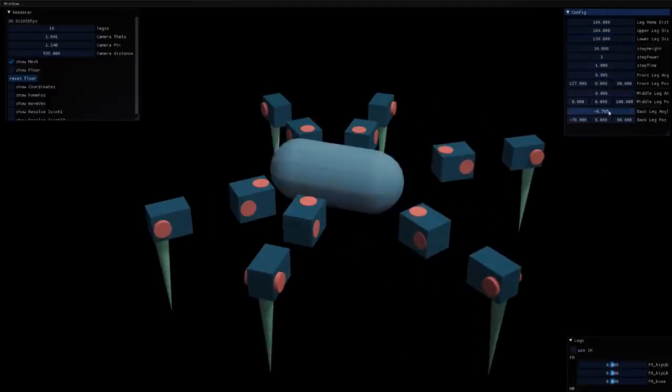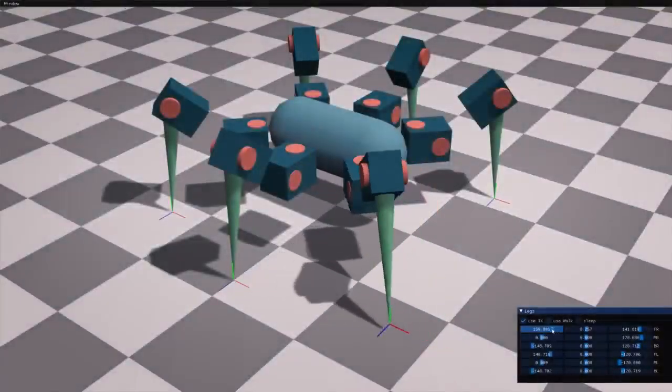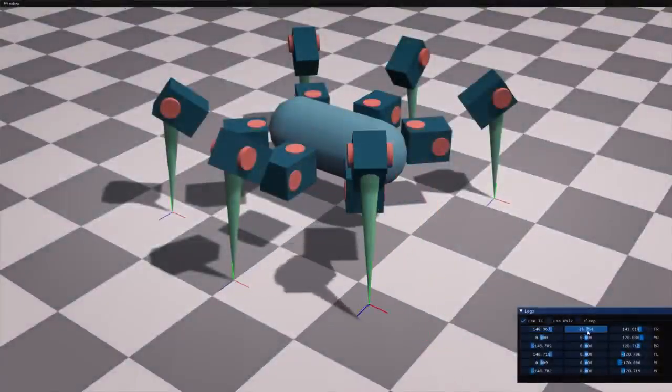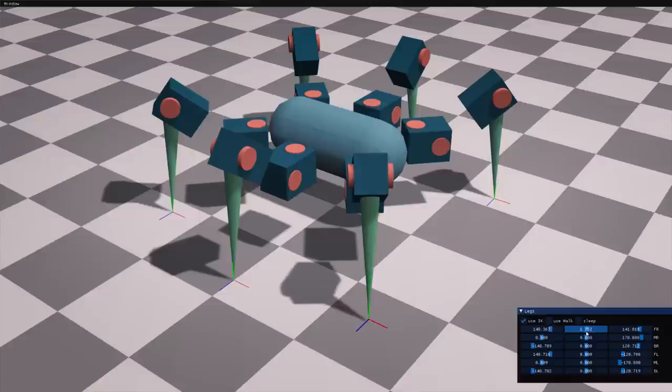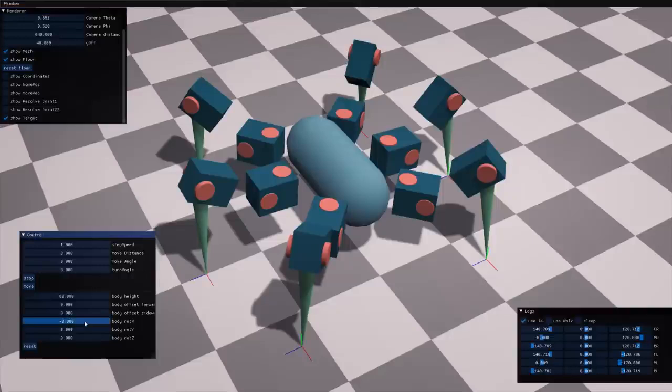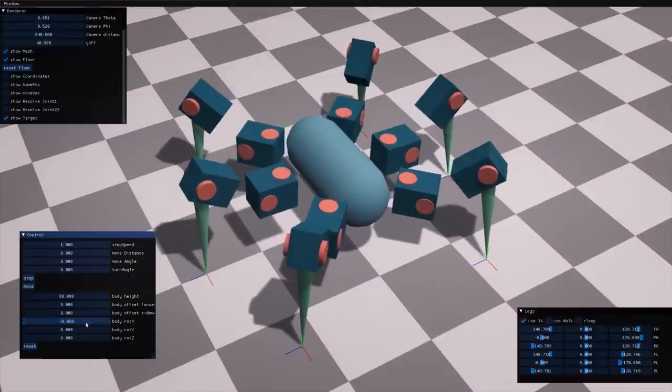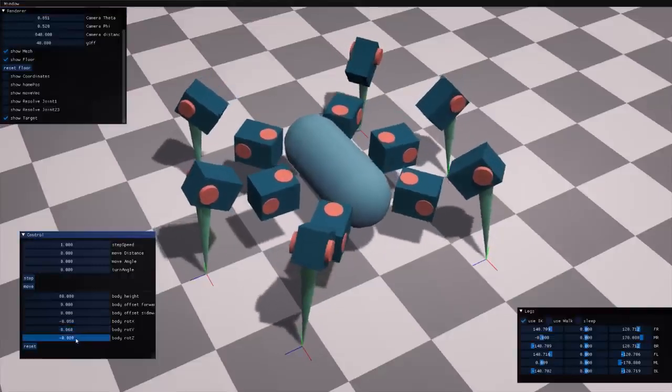So here comes the next step in play, inverse kinematics. Instead of controlling the angles of the motor, you just control the end position of the leg and let the computer resolve the correct rotations for the motors. If you do that correctly, you end up with a very flexible model.